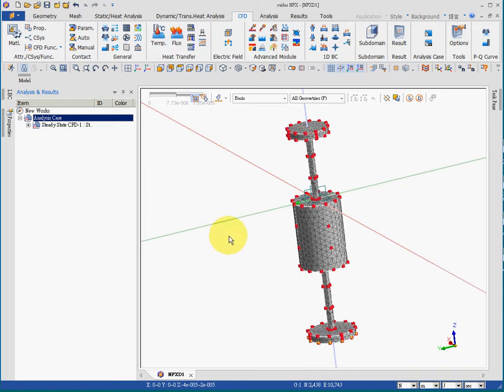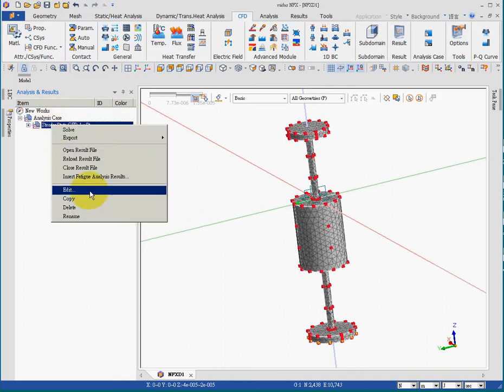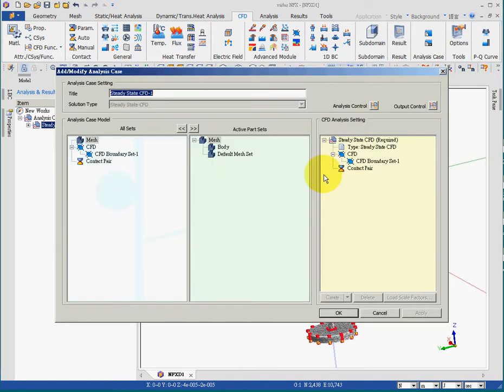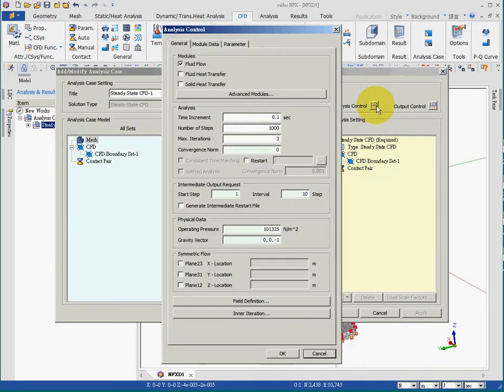The first thing is the initial condition, for example, initial temperature, initial pressure, velocity, etc. And the second thing would be the time to calculate. For example, you are calculating an hour or 2 hours of time. So these are the differences. For steady state condition, we don't need initial conditions or calculation time.